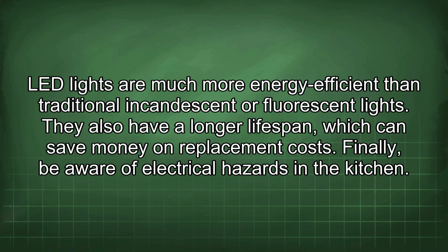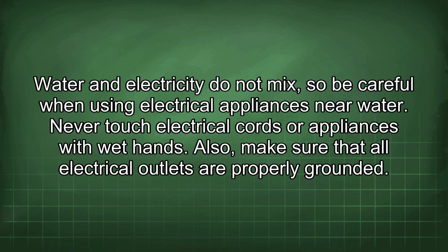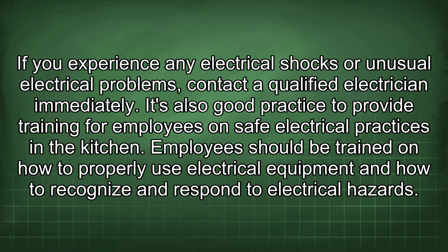Finally, be aware of electrical hazards in the kitchen. Water and electricity do not mix, so be careful when using electrical appliances near water. Never touch electrical cords or appliances with wet hands. Also, make sure that all electrical outlets are properly grounded. If you experience any electrical shocks or unusual electrical problems, contact a qualified electrician immediately.